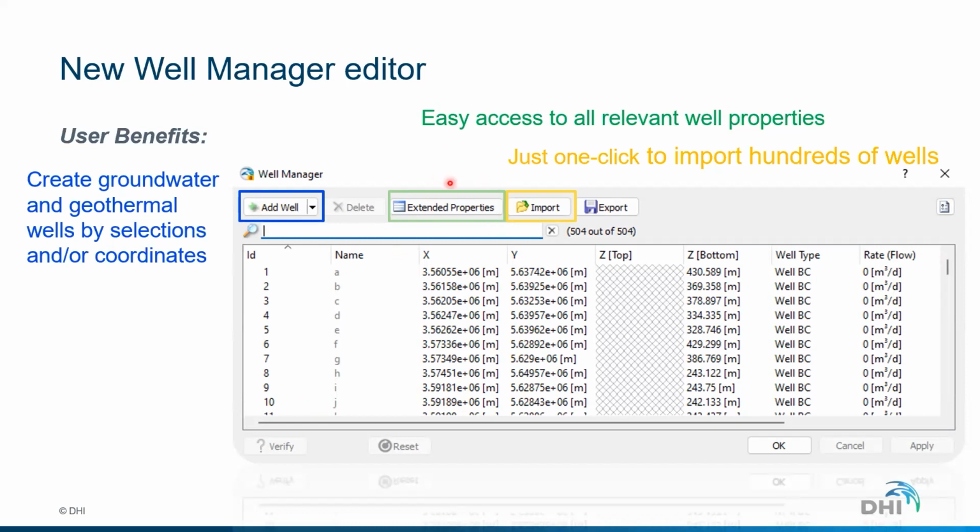It has a section called extended properties where you can provide properties of multi-layer wells, but also define boundary conditions for the mass transport. So if you are doing injection modeling cases, where you have a well BC linked with the mass concentration in FEFLOW, you can just do it directly from here. You don't need to assign the boundaries twice. So this is nice. This already exists since November.